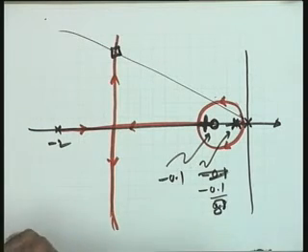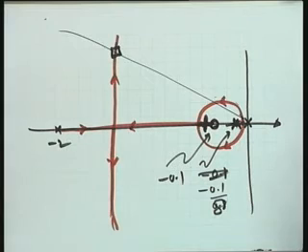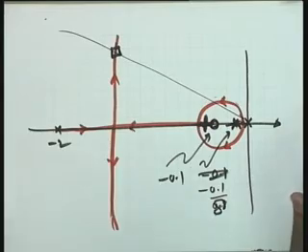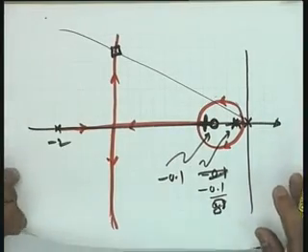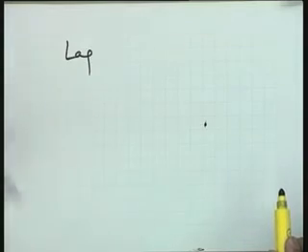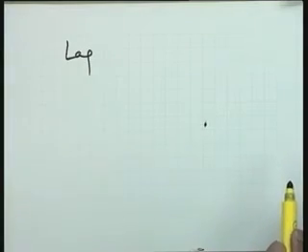So I conclude and want an answer from you that if the transient performance of the uncompensated system, by uncompensated I mean only gain adjustment is allowed, is satisfactory, in that particular case you will like to go for a lag compensator and you place your poles and zeros so that steady state performance is satisfied.